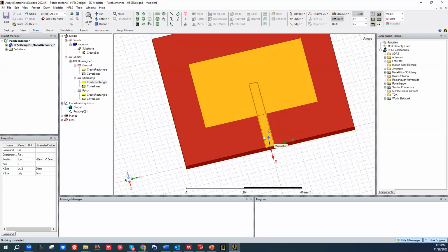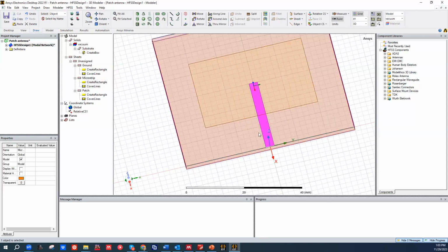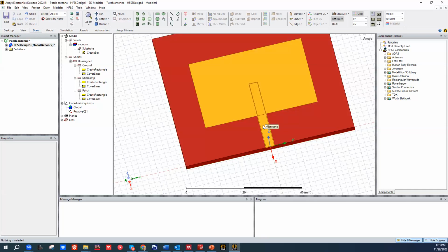So we will normalize the characteristic wave impedance of this microstrip to 50 ohm, which is the typical number for coaxial cables and for outputs of generators, etc. So it's going to be 50 ohm here, but this patch definitely has another input impedance.